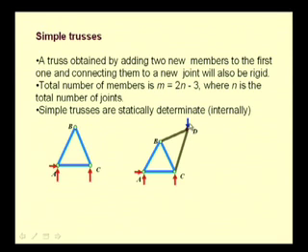If we consider the free body diagram of a single joint, let us say joint D, then for the joint D to be in equilibrium, the sum of all the forces has to be 0. The moments are obviously 0 because all the forces are concurrent at D. So, these forces do not cause any moments, and so the summation of moment is obviously 0. But for the joint D to be in equilibrium, the summation of the forces has to also be 0,